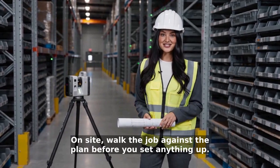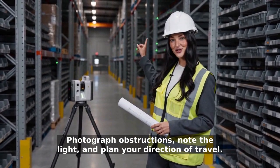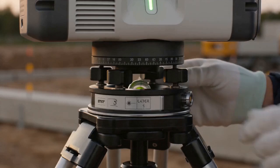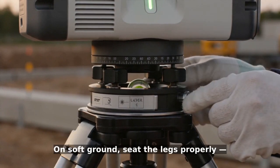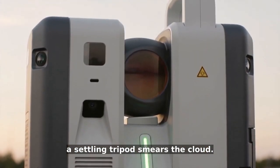On-site, walk the job against the plan before you set anything up. Photograph obstructions, note the light, and plan your direction of travel. At each station, plant the tripod firm, mount and lock the scanner, and level within 10 degrees. On soft ground, seat the legs properly. A settling tripod smears the cloud.